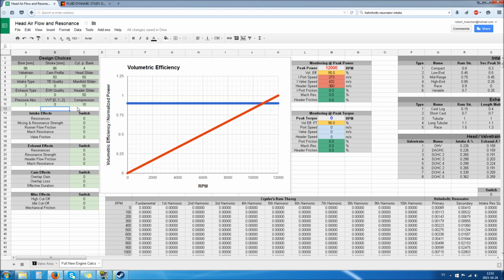For very low revving engines, like eco engines, you still have more than 180 degrees, something like 220 degrees of effective opening of the intake valve, for instance. And then for really high revving engines, you would have durations of up to like 280 degrees of crank angle, which sounds kind of insane, and basically is. And that creates another thing, that is overlap, and that's why we are here.